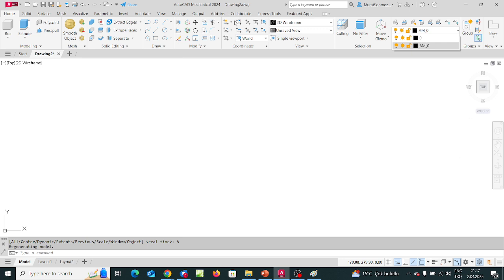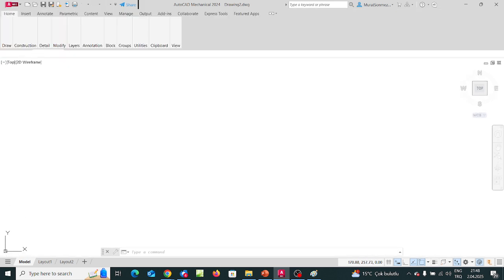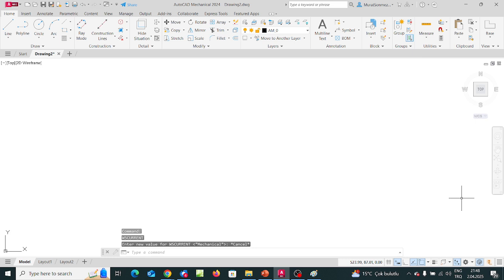Okay, since the transfer line tool of the software is available in 2D mode, well, at present from the ribbon it can be seen I have the 3D tools along the ribbon, so the mode is 3D mode. I'm going to switch the mode from 3D to 2D. Click on this listing arrow and select mechanical option. Yes, I can change the mode from 3D to 2-dimensional.